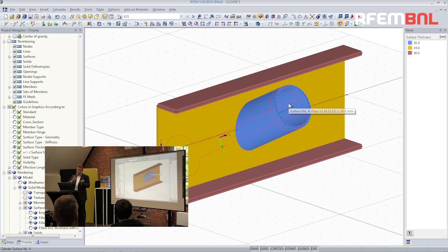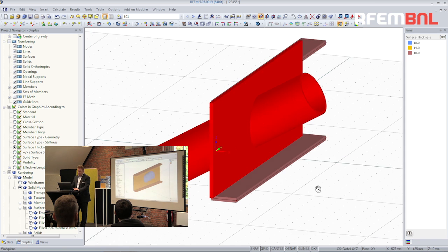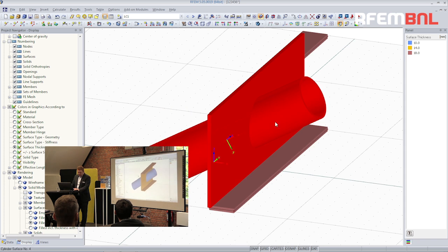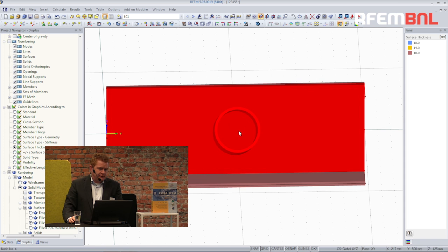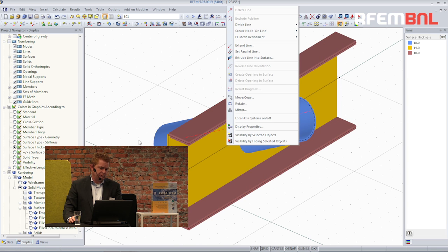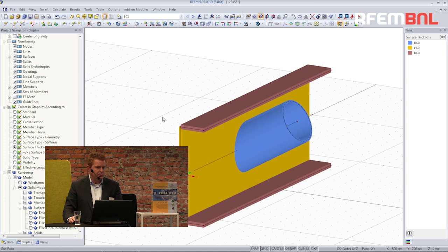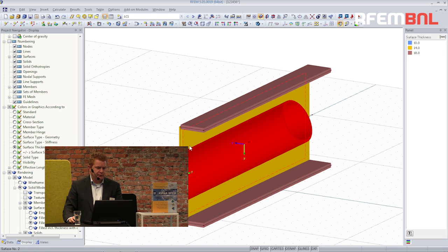anchor, with the plugs on top of it. So if I add the pre-stressing load here, it could maybe cause really high stresses in this case. So what I will do is divide the two surfaces and create an intersection. Because if I look here, there's a surface inside. It's not there.